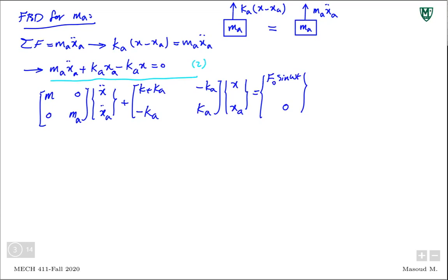Now my goal here, in order to design this vibration absorber, is to find the correct values for Ma and Ka. Remember, this is the absorber I'm attaching: some mass, the amount that I should know, and some spring Ka, that I should know the stiffness for. How do I do that? Well, to figure that out, we have to solve these equations of motion for a harmonic input, and then take it from there. So here's what I'm going to do. We want to find a steady state, so I'm going to take a general form of a solution.